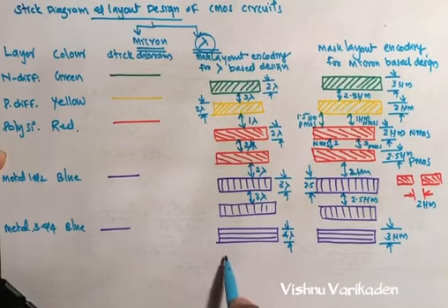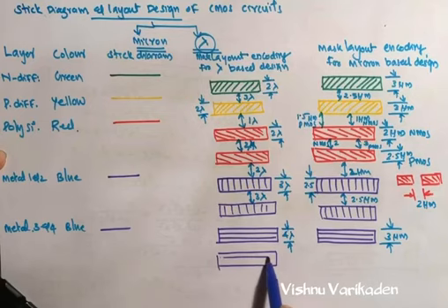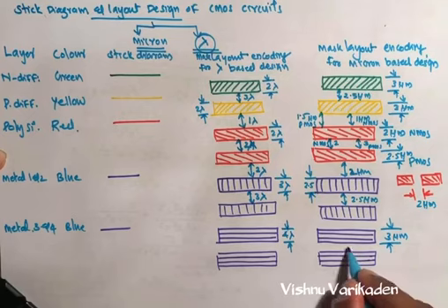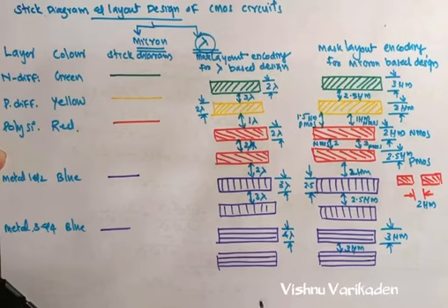So in between another metal and another metal, in the micron based design rule, this is 3 micrometer in between. So in between this is 4 lambda.